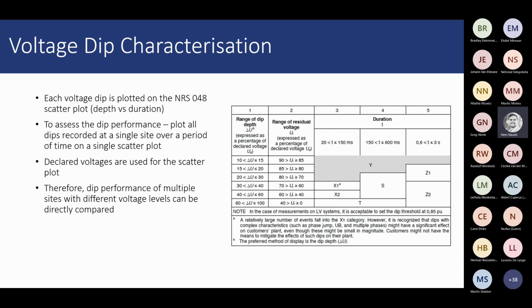So yeah, if you've installed power quality instruments on various voltage levels, and there's a big network or utility Eskom fault, for example, you'll be able to see how that propagated through your network and impacted your customer or the LV side of a network. That's why this scatter plot becomes important over time: to compare events at different points in your network, and also to get a good understanding of the characteristic performance of your network, what sort of events you normally get, and you'll also normally see patterns. It could also be seasonal. For example, here in the Western Cape, we expect more rain in the winter periods, but in the summer we get more wind. All of that can play seasonal effects on how the networks perform during that period. And if you measure over a long period, you can benchmark that quite accurately.